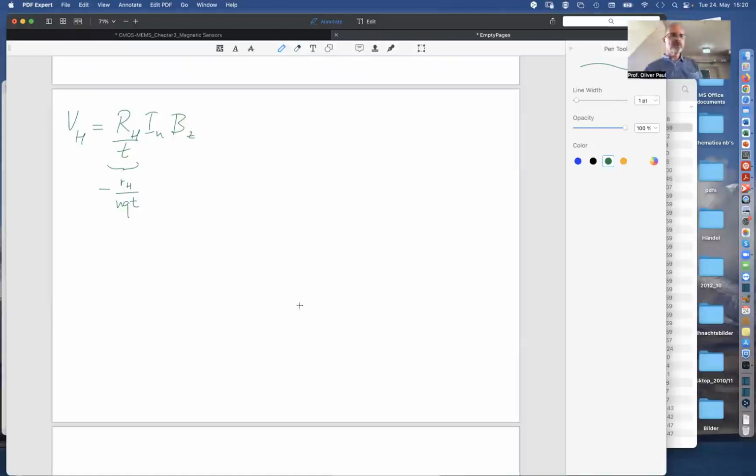So when you look at this, how can we interpret this? This is like a charge density, volume charge density times the thickness. That's a sheet density of charges times Q. That's the sheet charge density. How many Coulomb per square meter are there in this conducting layer? So the electrons, how many coulombs do they represent per square meter of area? It's kind of a sheet charge density.